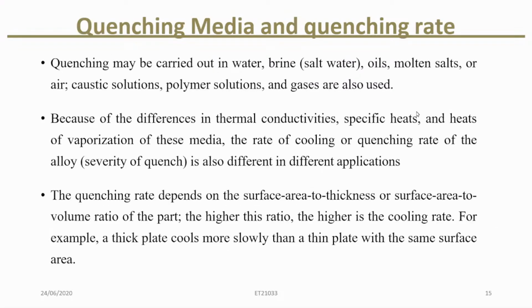Then after heating the steel, we quench it. Quench means cool it fast. So we can drop it into water, brine, or oil, or just blow air or gas. Some shops also use polymer solution or caustic bath.